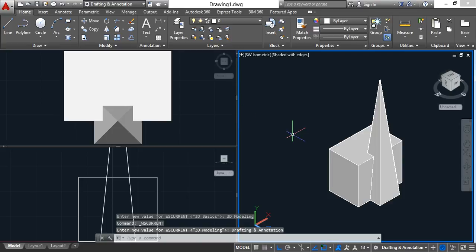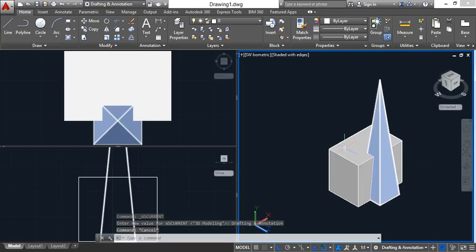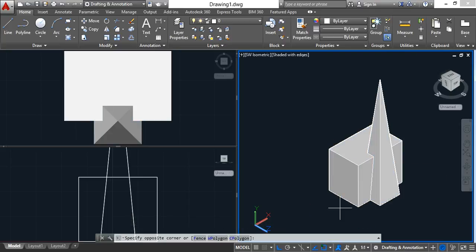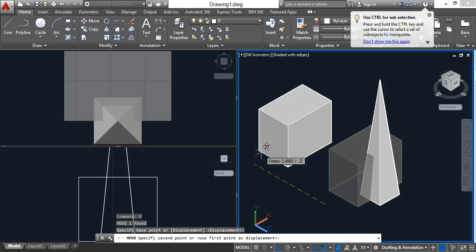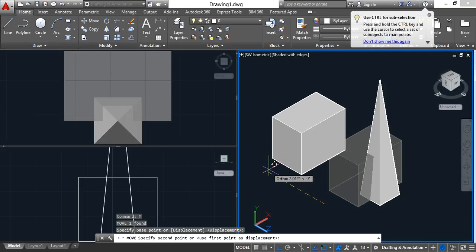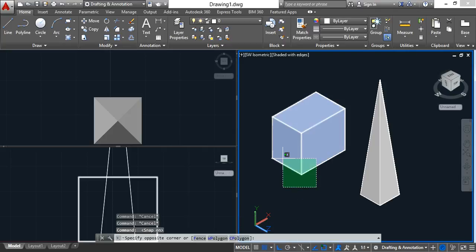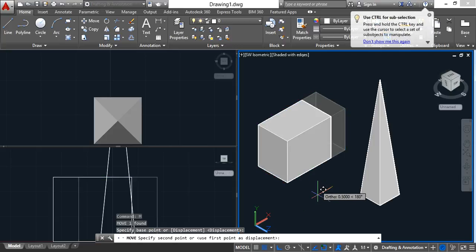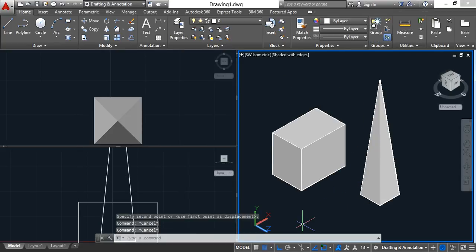Another thing I wanted to mention is, oh, it's a little laggy right now. This happens a lot when you're switching between workspaces. If I move this thing using the M shortcut, it's traveling along the XYZ, right? But what's also cool is you can travel along a specific grid. So if I have snap mode on, if I move this around, it's going to try to snap to a three-dimensional grid that's preset. So it looks like I'm lagging, I'm actually not.